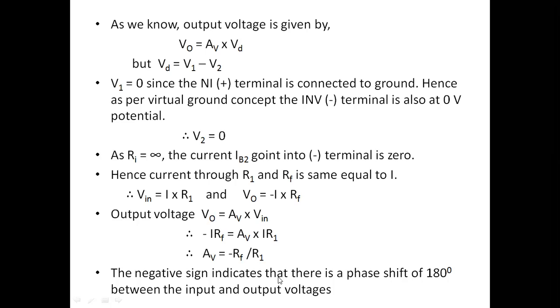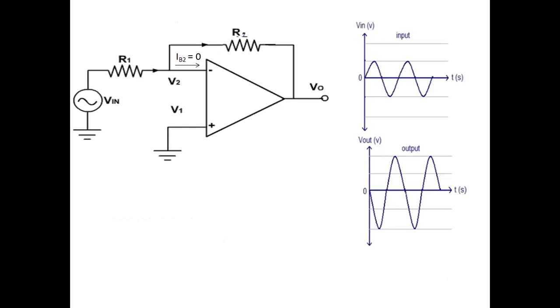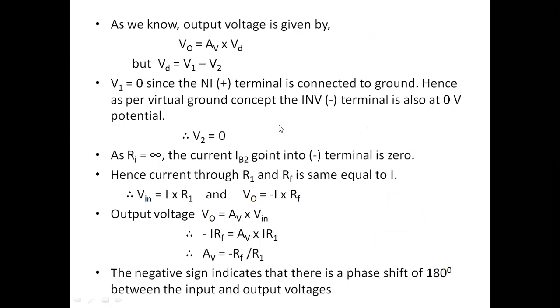Okay. So here, Sneha, now we are studying about the inverting amplifier. Inverting means what? If we are giving the input to the op amp, it will give us a 180-degree phase shift with the input. That output will be amplified, but there will be a 180-degree phase difference between output and input. At that time we call that amplifier inverting. So here we give the input to the inverting terminal, so we will get the inverted output.